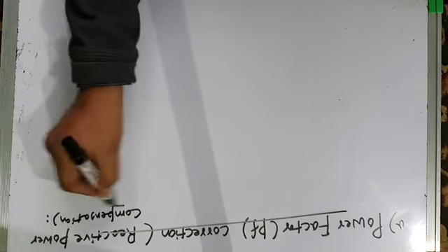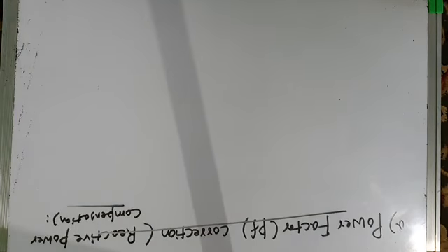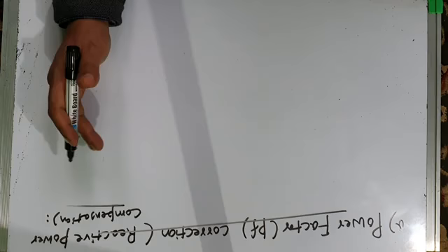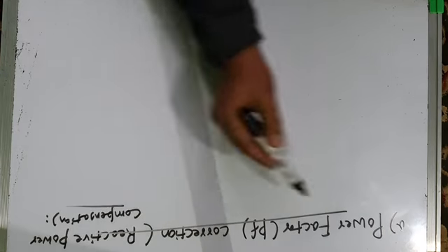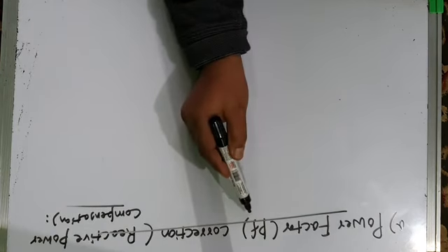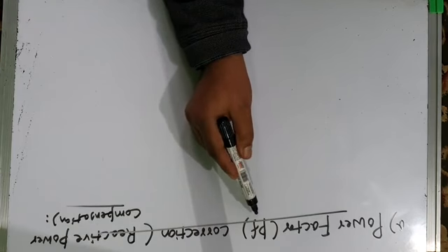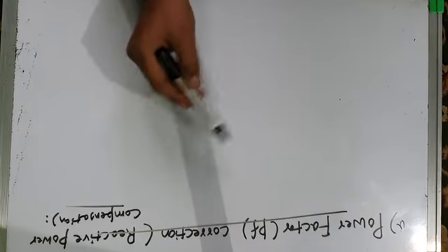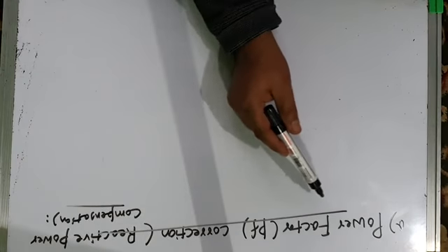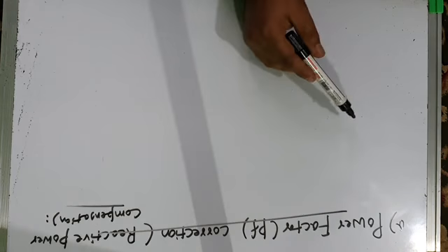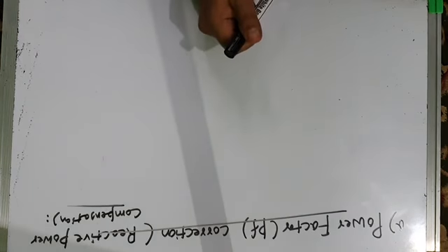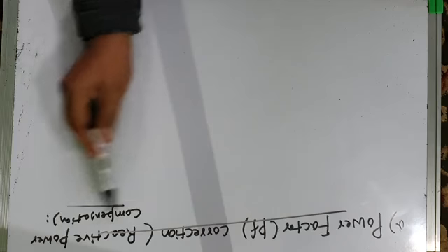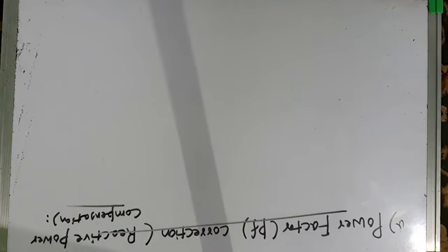Let us see the working of the compensator, how a shunt compensator can be used, designed, connected across the load for compensating the reactive power or for improving its power factor. Say, let us assume the power factor has to be improved from, say, 0.6 or 0.5 to unity. So our first power quality problem that we have taken is poor power factor, and let us see how we can use a shunt compensator for correcting the power factor. That means for reactive power compensation.